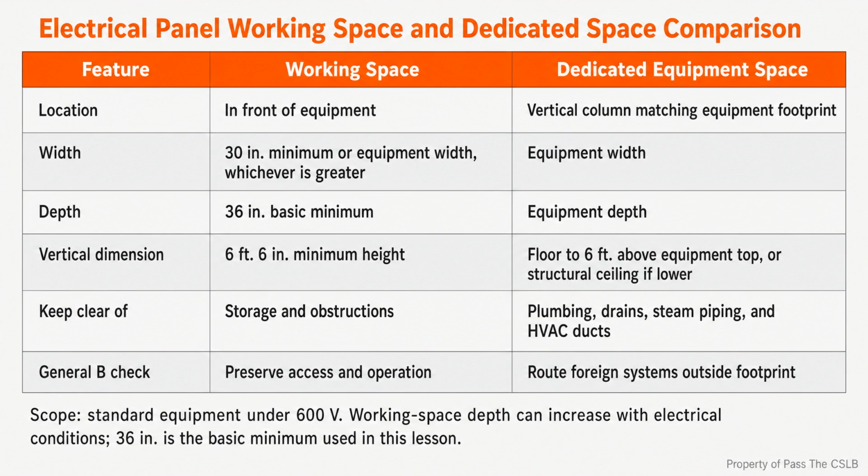A useful supervision habit is to inspect the panel twice. I inspect when the electrical work is ready, and I inspect again after the surrounding finish trades have worked. The second look catches blocked access, overspray, plaster dust, stored material, and newly routed systems that were not present during the first inspection.